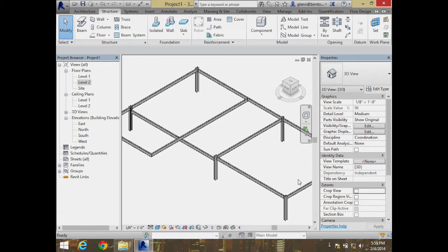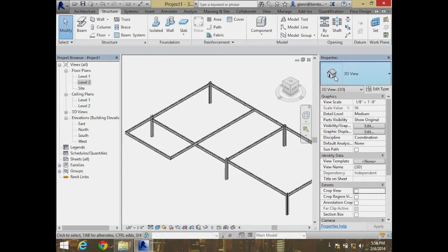So if I want to put some intermediate supports in here, given the heights, I would think about actually running them left to right so that they can all ride at the same height, because I'm trying to avoid that lower piece down there. Okay, so I can have them spanning across here. There's a number of ways you can do that. And so what I mean, in terms of framing up the floor, it'd be something like this. So we have beams.